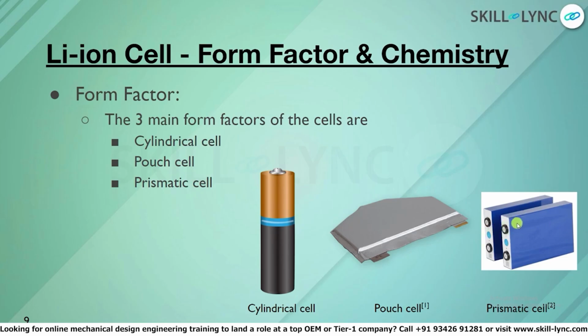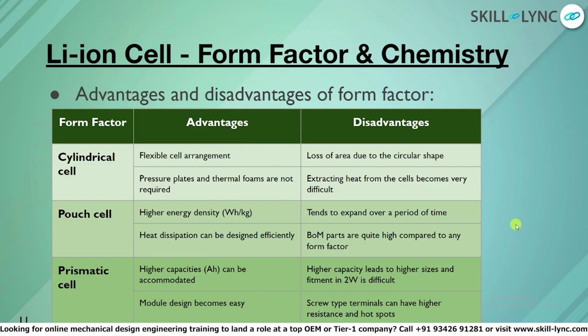So which means this doesn't expand like how a pouch cell expands. So you don't need a lot of pressure plates and a lot of holding materials for a prismatic cell as compared to a pouch cell. So that makes the whole design a little bit easy. And then one disadvantage is sizes.